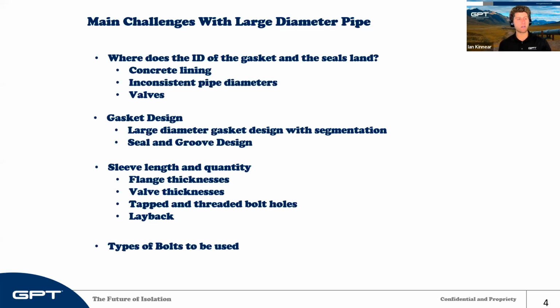And we all know the story. Some of these take days of installing one gasket. You have 60 bolts, 2-inch bolts, really high torque. We finish, hydro test, and it leaks. And I think nobody rips their hair out more than when something like this happens, because now you have to uninstall, replace the gasket. You might have to wait a time for that gasket to be made, reinstall again.